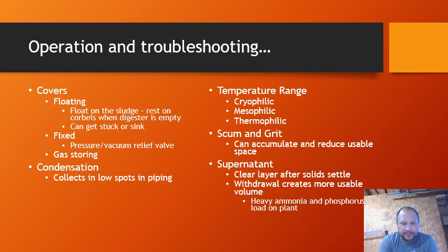The last type of digester cover with anaerobic digesters is a gas storing digester cover. These kind of resemble balloons, and they'll inflate and deflate as gas pressure builds and allow storage of methane gas in the digester, generally for use in creating energy.